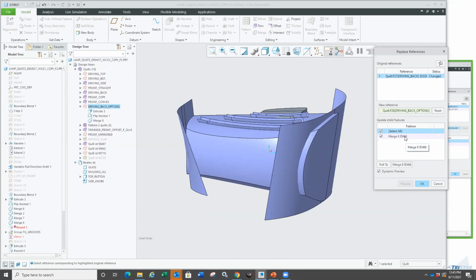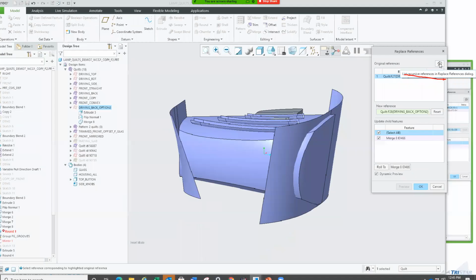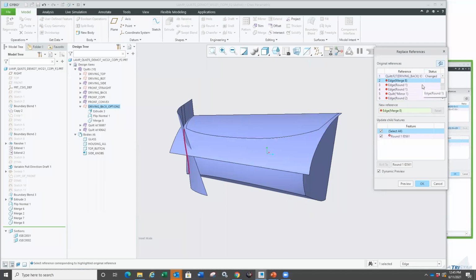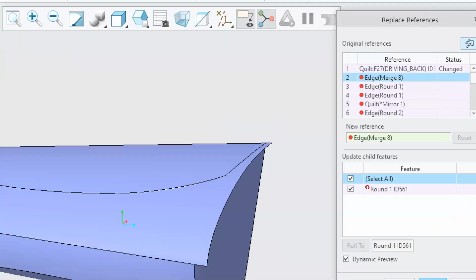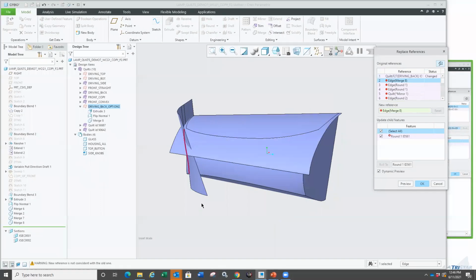That's one of the main pain points sometimes when you make drastic changes in Creo, right? There's going to be parent-child, children on top of children. It all comes down to modeling best practices. But here, this lists the recursive references, and it's pretty nice where it automatically goes in to the next level, and it tells me these are the missing ones, right? There it is. Now, missing reference has been there since, again, Creo 3.0, it showed missing reference. That's not a big deal.